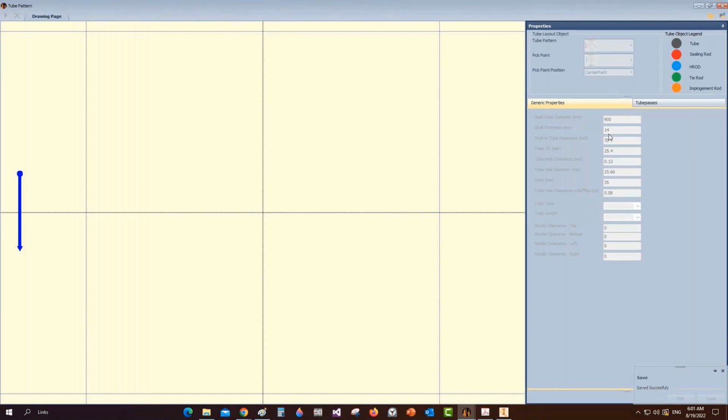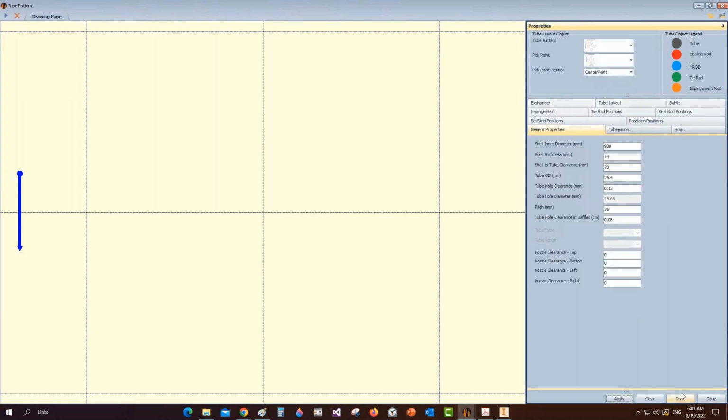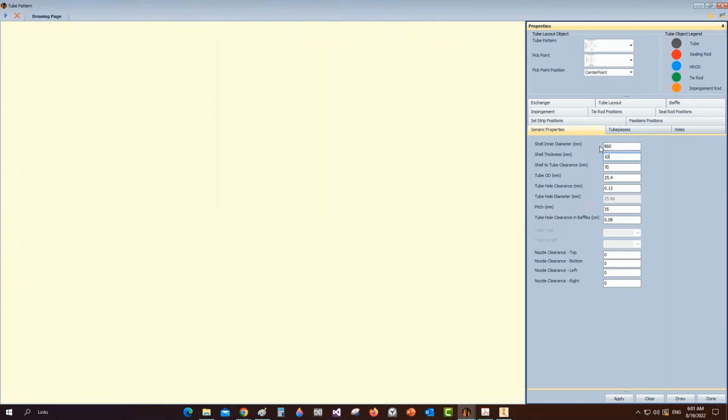and from the tube bundle, we will modify or define the tube bundle arrangement. Okay, so from here, let's create an editing and define the dimensions of tube in millimeters. 50. Let's accept that. And for the top clearance, 100.